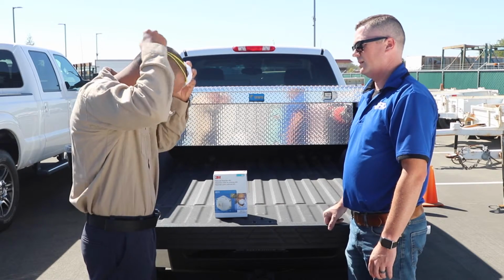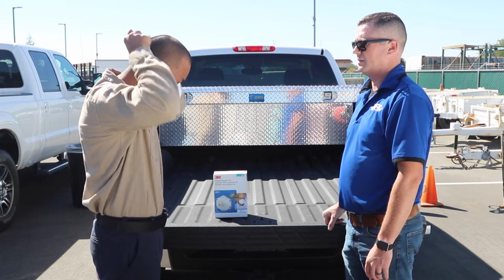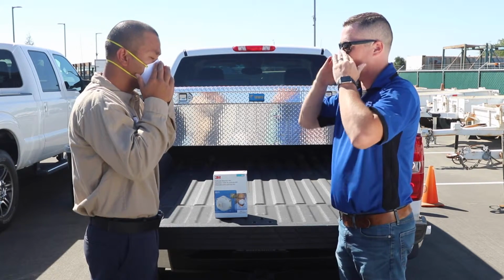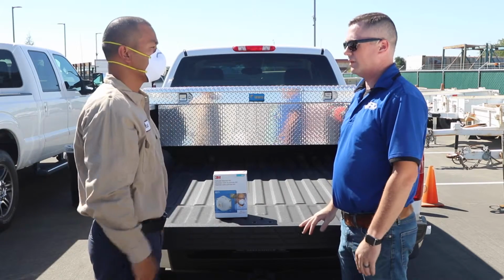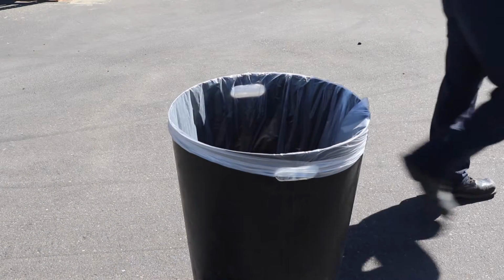With all of that said, the question remains, what type of respirator should I use in different situations? There are many different makes, models, and types of respirators on the market. We'll be focusing on the more common types that you could use during a job task. The most common type you will use is the filtering face piece, more commonly known as the dust mask. These are negative pressure respirators with a filter as the main part of the face piece. They're designed to be a single-use respirator and should be thrown away after use.